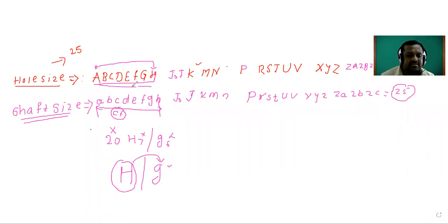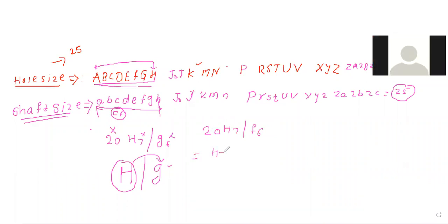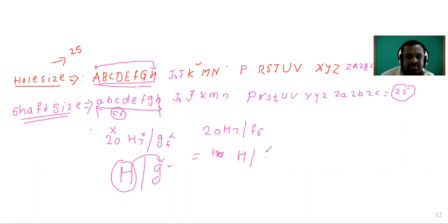Does it come to your attention? Yes, sir. Then tell me the second example, I will write down here: 20 H7/f6. Then tell me what is the fit? Clearance fit. Yes. Okay, just I will write here H, f.